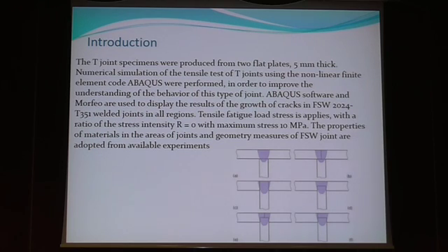Now, before we started experiments, we wanted to check what numerical simulation can give us. The most interesting question for us was if the crack would grow only to the base plate, or would it deviate and go at least partially through the stiffener. We are not considering only T-joints, we are actually considering plates with several stiffeners, as it is a more real structural case. Now, to go back to numerical simulation, nonlinear finite element code Abaqus was used.